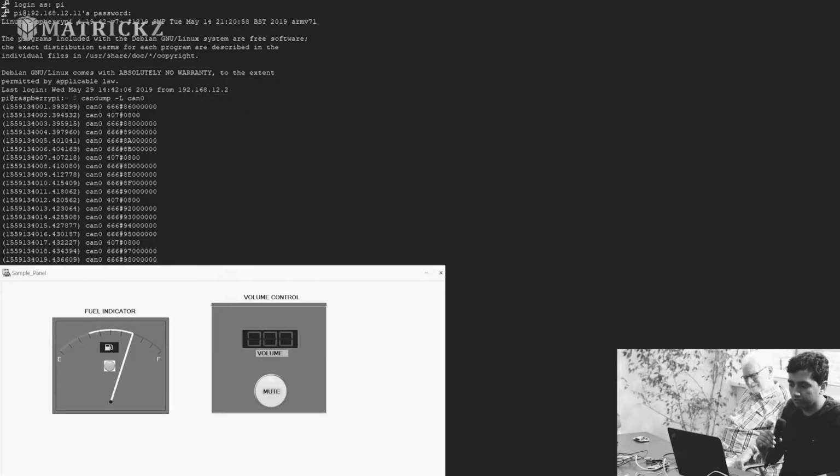As you can see on the screen, we have multiple messages coming on the CAN, and for a person who has not developed these programs, who has not programmed the ECUs, these are just messages. If you look, there are two different arbitration IDs that we can see.